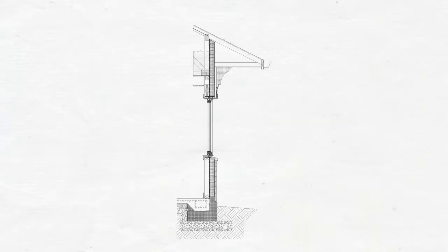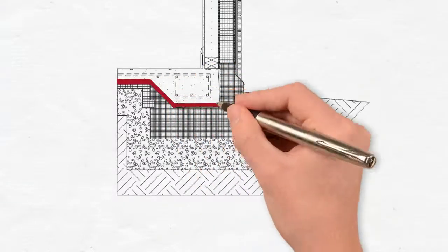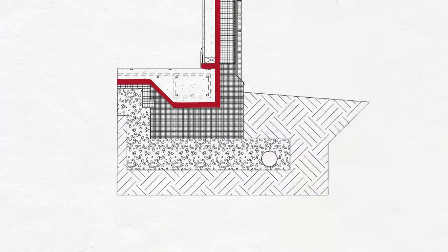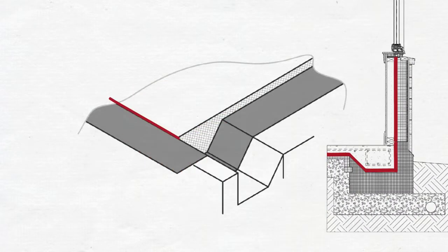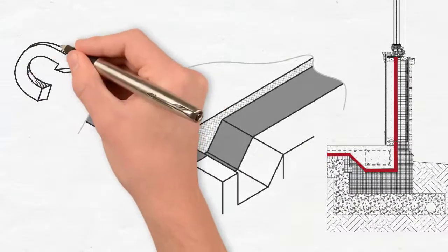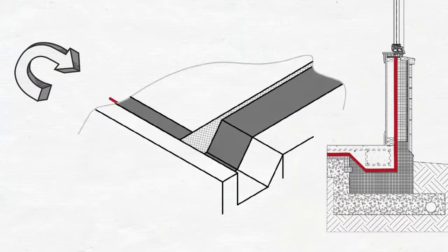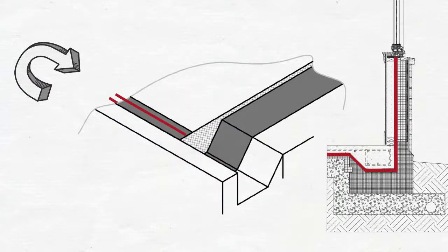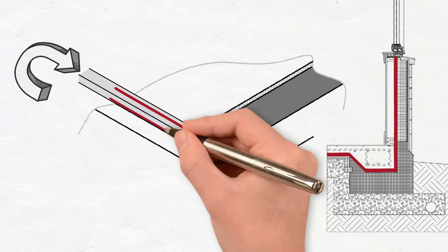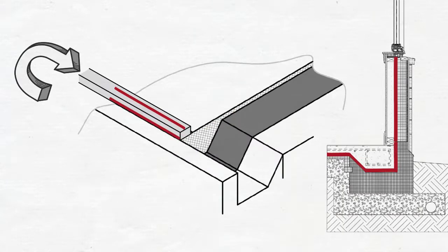In the example of our simple building design, the air barrier would be sealed at the connection between the slab and the wall. The sealant is placed on the slab. Then the air barrier material from under the slab is folded up onto the slab and embedded into the sealant. We put sealant again on the top of the rolled up air barrier. Then we embed the bottom plate and put sealant again on top of it, and at the joint between the slab and foundation. After that, the wall panels can be set up.